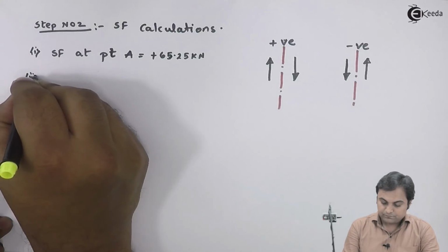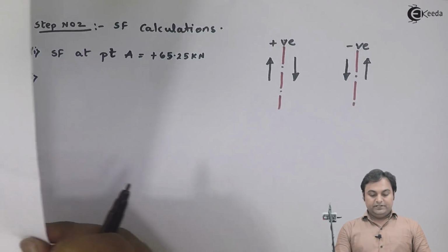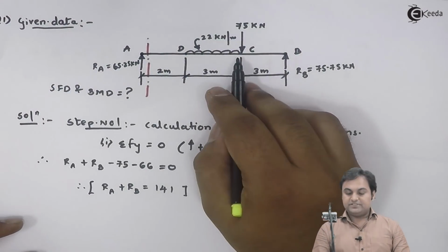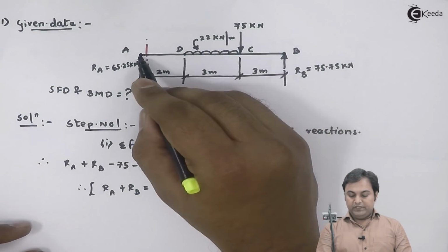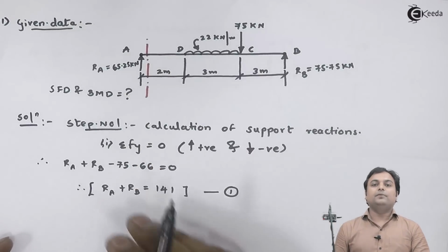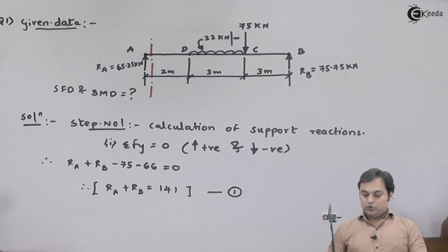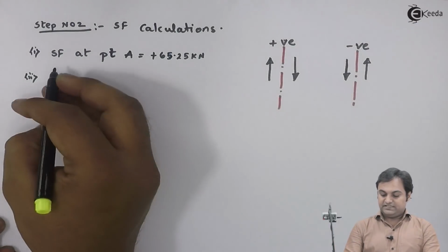Next, I will be calculating shear force at point C, because between A to D the shear force will remain constant as there is no load between A to D. So after this I will say that SF